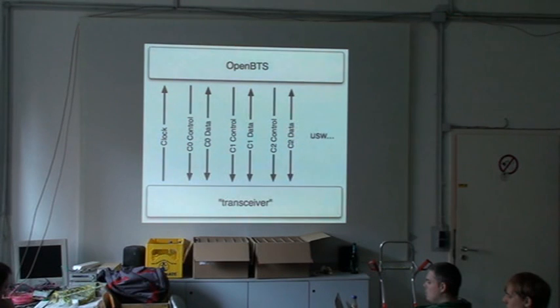It contains an estimate of the power level at which the signal was received, and then it contains the normalized soft signal pattern, normalized to an 8-bit scale. So if you want to know the actual absolute power level, you can look at the header information and know what the power level really was. But what's transmitted in the burst is normalized. That's the interface. It's not that complicated.